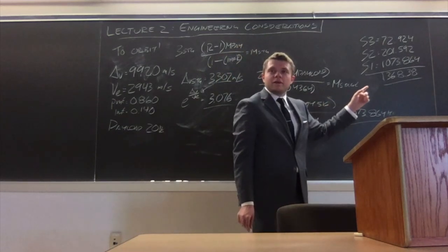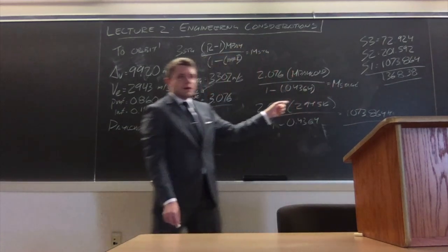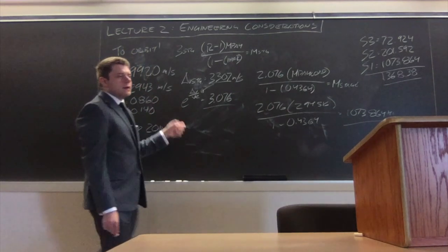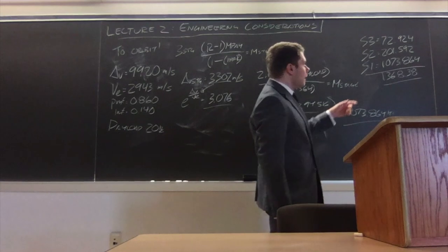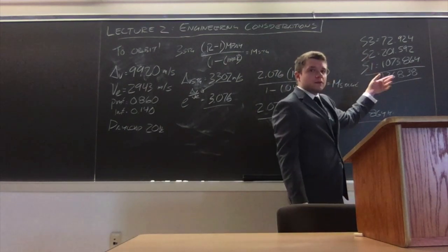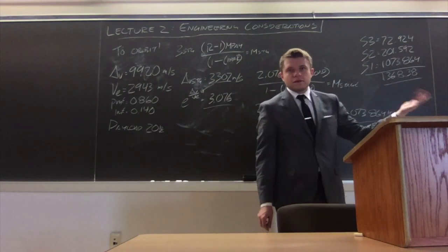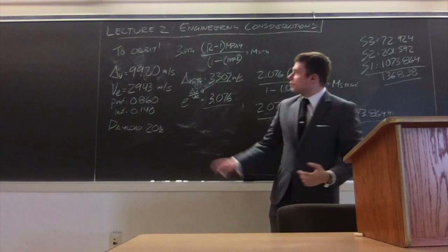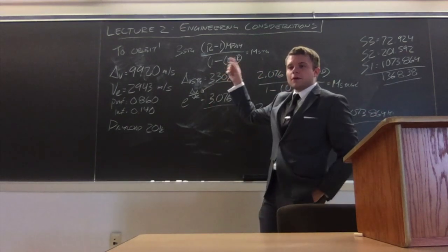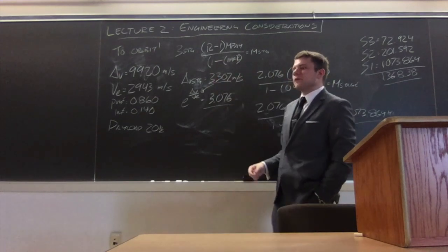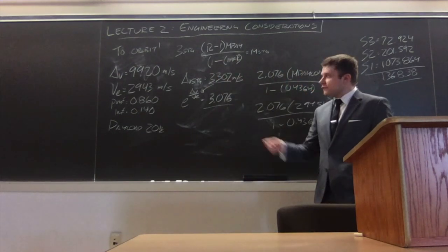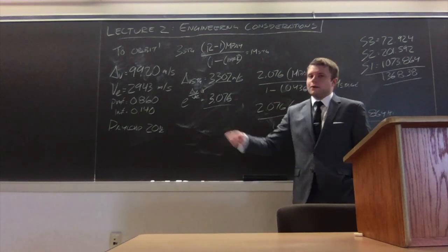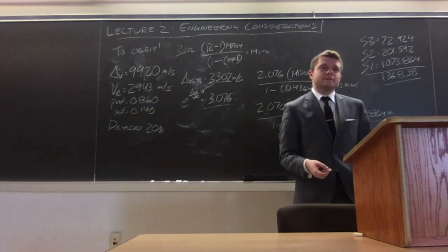We now can calculate exactly how much propellant is loaded in each of these stages by taking the propellant mass fraction from before and plugging it back in. And we can calculate the total inert mass of the rocket by adding up the inert mass fraction times all these stages, minus the payload mass in the system, of course, and going from there. That's why this is a really important way of looking at it, because you actually start making real-world considerations when you're playing with these numbers. And this is a system that, if you could optimize everything and work it out perfectly, would in fact get you a 20-kilogram satellite to low Earth orbit. Pretty cool, huh?